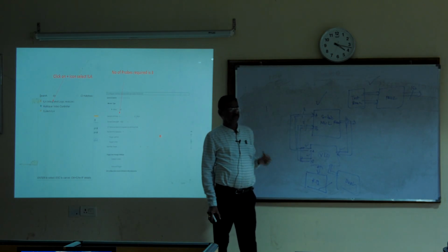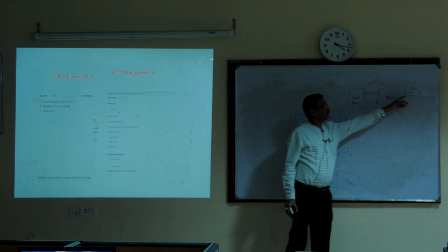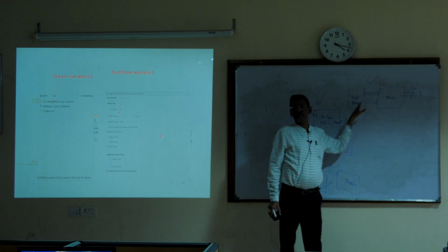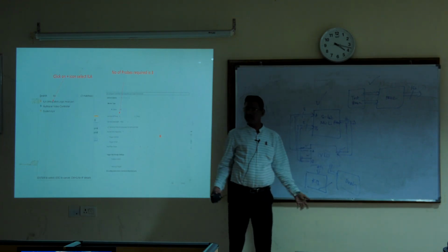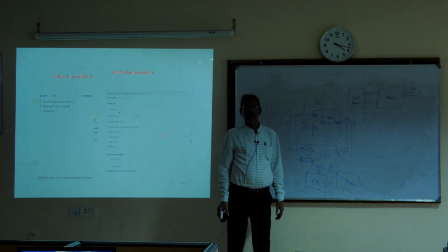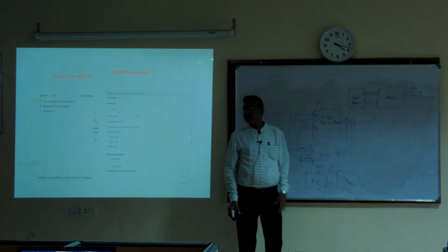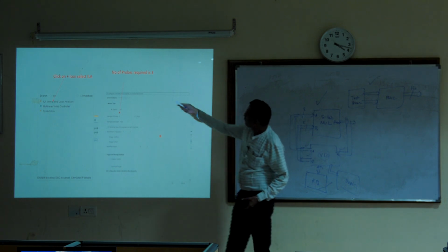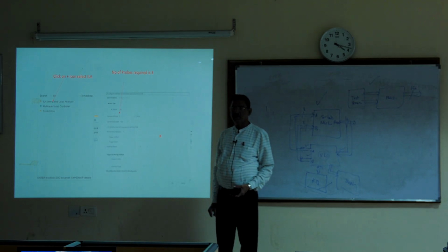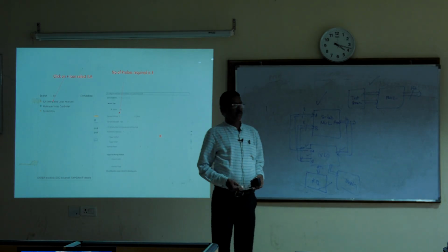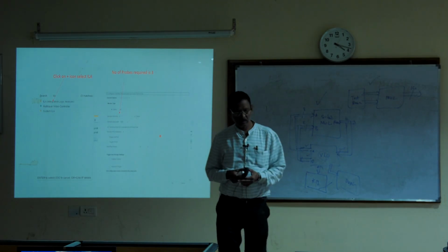If you want to see waveforms also, like in our simulation, where we have 4 different test cases and we are seeing the waveforms, this multiplier is a combinational logic, not a sequential logic. If you want to see the waveforms, then you have to use one more IP. That IP is ILA, the integrated logic analyzer. By using that IP, we can plot the waveforms also. Okay?